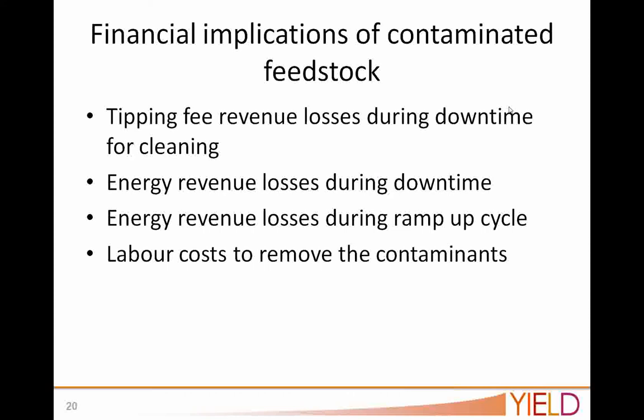The other part of that is that over time, that grit becomes a hard cake, a hard mass at the bottom of the digester. So oftentimes you may have to drop a mini excavator or a Bobcat in there in order to scrape it out, which complicates the problem again.